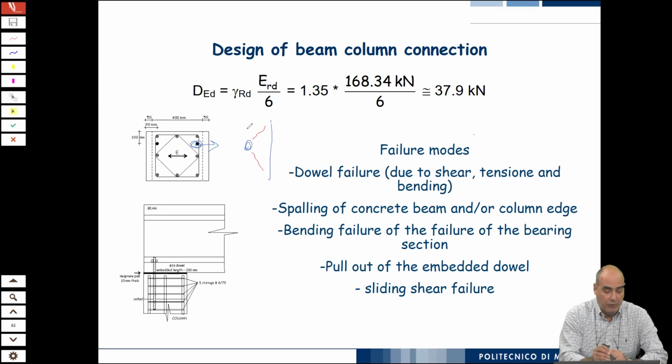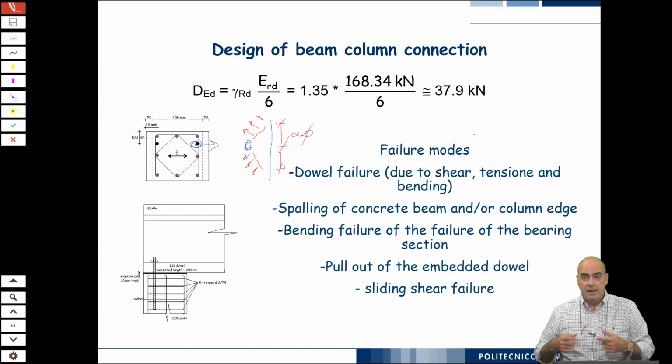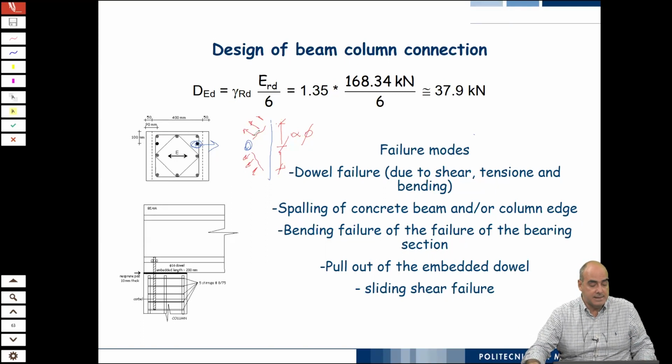The maximum force is very easy to compute. You estimate this width, which is a certain alpha times the bar diameter. At the ultimate limit state, you will have fully cracked, so the maximum value is when there is tensile stress equal to the strength everywhere. So you calculate tensile strength times the length of these two segments, projected in the direction of the force, and you have your maximum force due to this mechanism.